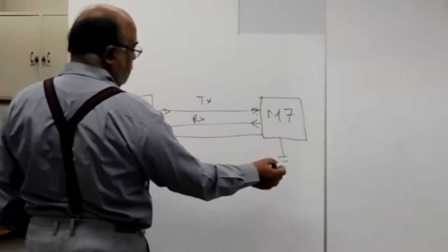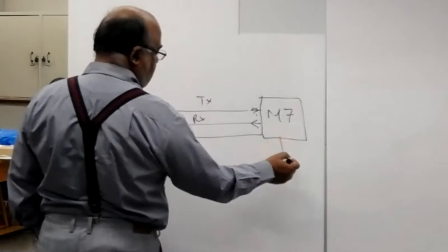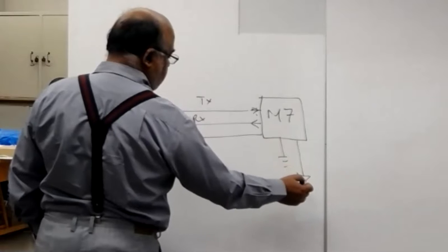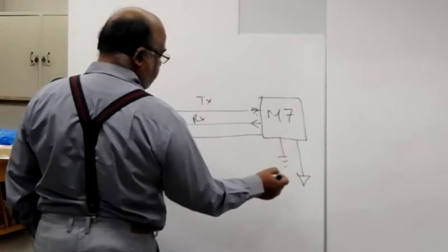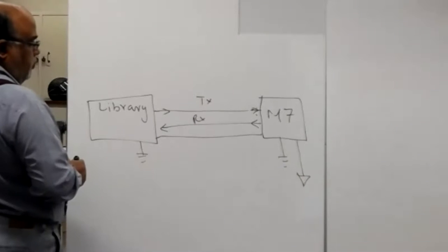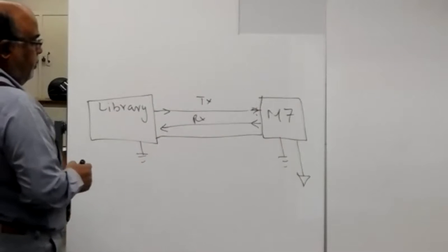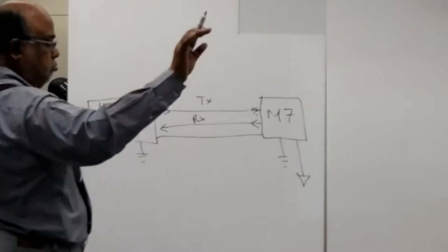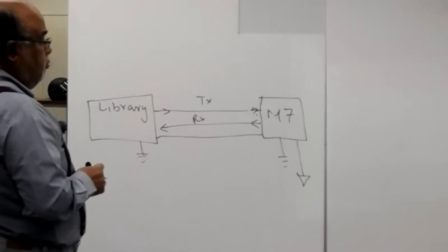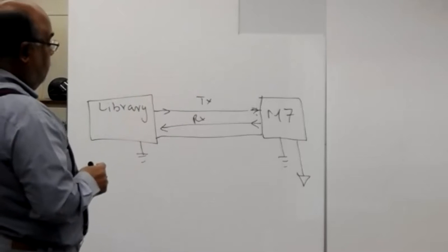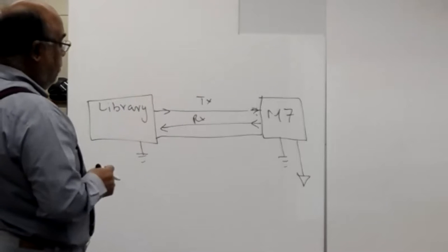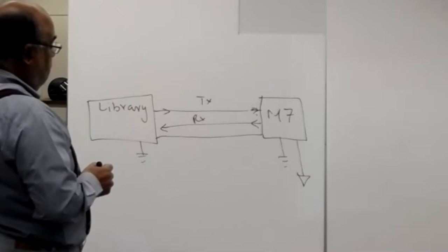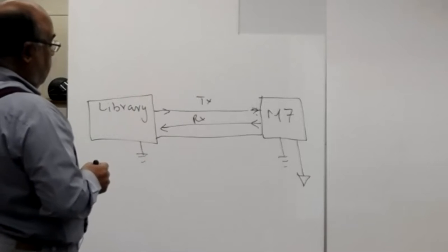So it is connected to the ground of the building also, which is earth. Every neutral point is connected to earth on every pole. On every pole, they have done this, they have earthed the pole, so that people don't get an electric shock.